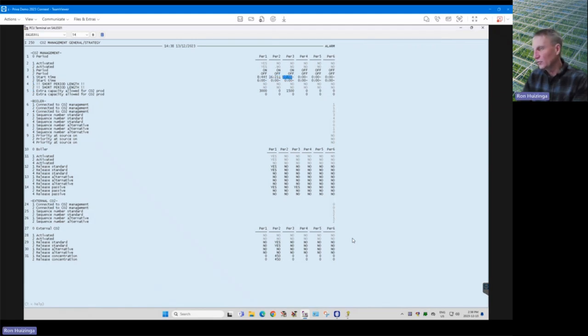I've got too many lines on this page, sorry about that. So maybe we make 4. The warmest, latest part of the day, when my buffer tank is probably getting full, like 1,400 hours. So for the last couple hours of the day, I allow my liquid CO2 to come on, but only if it drops below 450 in the greenhouse, because of course liquid CO2 is expensive and you don't want to use it. But if you have inexpensive CO2, then you can make those numbers a lot higher for different priorities. Typically that's how most people will run it.